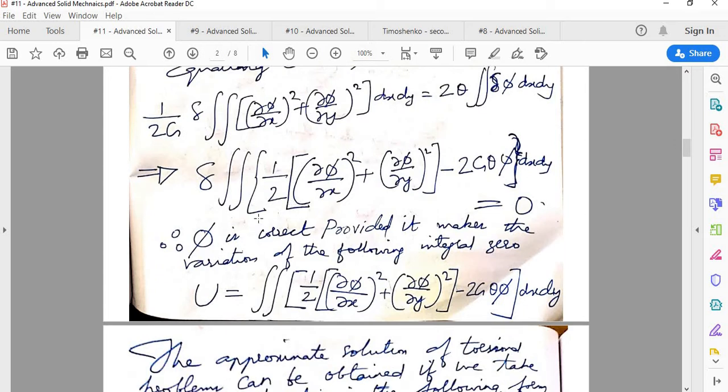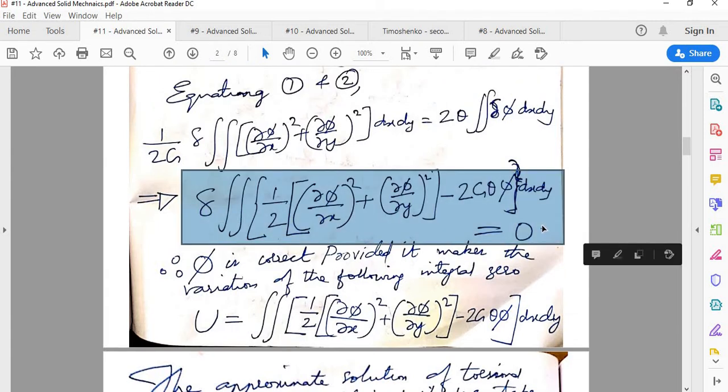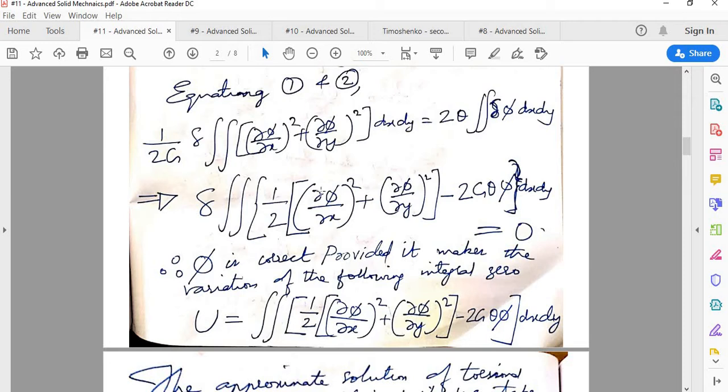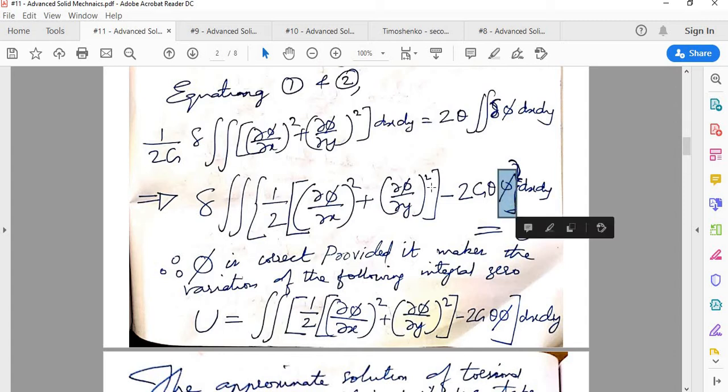Okay, so our solution corresponds to this equation that we are trying to solve. Remember, in this expression, the only variable is again phi, right? So phi, or the stress function, is our pivotal point, whether it is the stress approach or the strain energy approach. Other things are known. If you recall, whatever we have done so far with the stress function, initially it is guesswork, right?